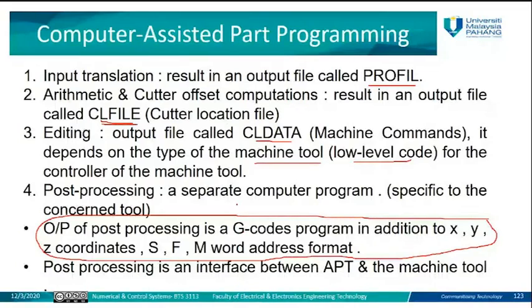So the same as in the case of the CAD and CAM. In the CAD and CAM, the programmer will not write any code. He will only make drawings. He will enter coordinates. He will do drawings, 2D, 3D drawings, and so on. He will define all parameters. Then the software itself will generate the G code that will be sent to the CNC machine. Okay. In the manual part programming, the programmer is the one who is going to develop G code.